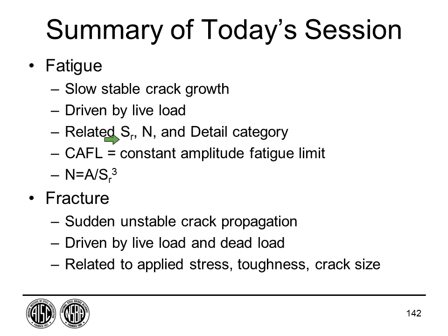This is the load side. How big is the stress range? How many times? This is the resistance side of the equation. If I can keep my stresses below the fatigue limit, well, everything's okay and I would not have damage. But if I do have high enough stress ranges, I can simply calculate the life with this simple relationship.